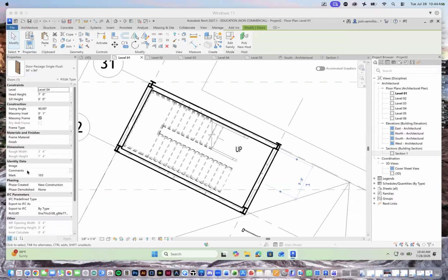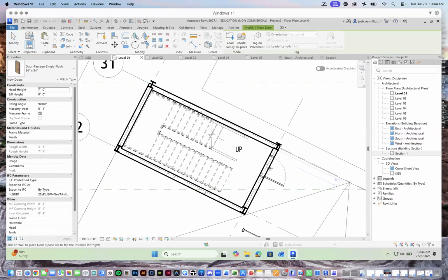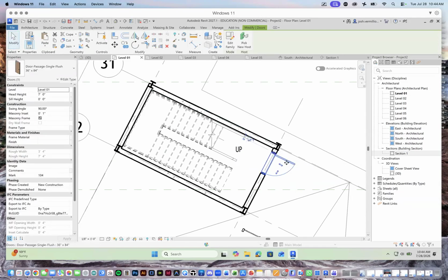Here, let me just close that. Architecture door. So in this case, I put a doorway here. I would swing it out that direction. Right. Away from the direction of egress, right? What happens if this was going the other direction? Let's say it was going in this direction, right? What happens is if you have four or five people racing to the door down the stairs, and then you press against this door and it's supposed to swing in instead of out, you start to crush people, right?